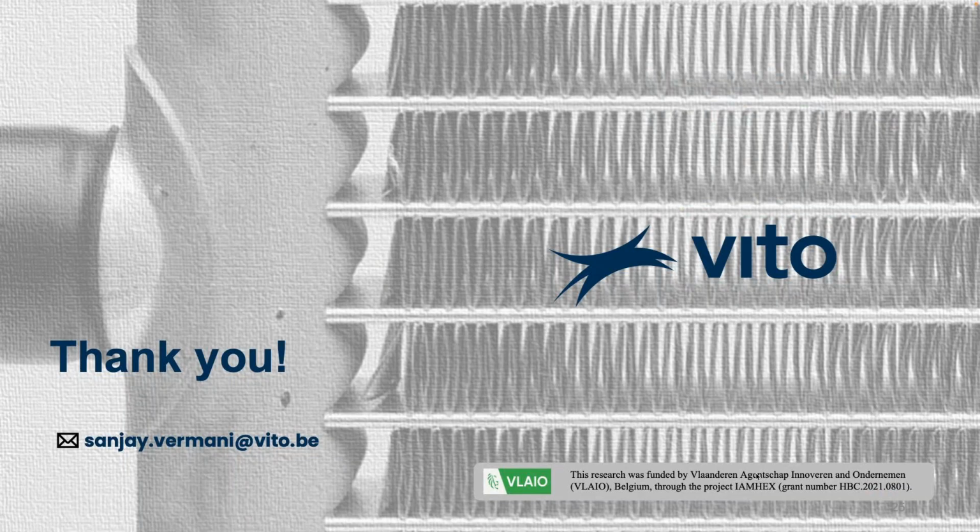Yeah, I think that's a very valid point. So I think that's a feature of this method, or let's say a drawback of this method, is that where is your boundary? So a typical approach which is considered is that, for example, you have gotten this design, you take an isosurface, for example, typically it's 0.5 because it's the middle region. You extract it, you do a body fitted mesh analysis, you compare your objective, you see is it the delta that you wanted, and then you try to move forward with the manufacturing. But indeed, if it's 0.5 or 0.8, there is no one answer to that, unfortunately.